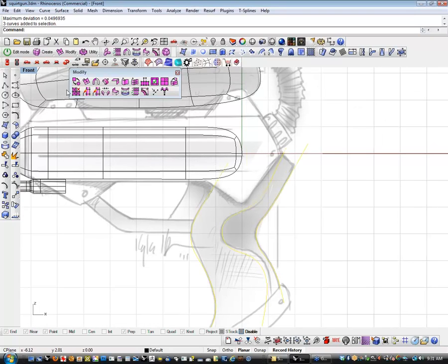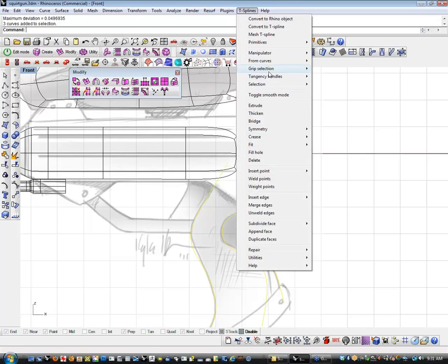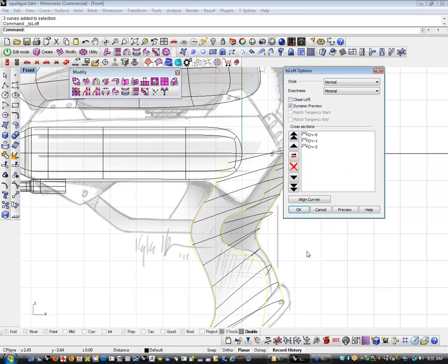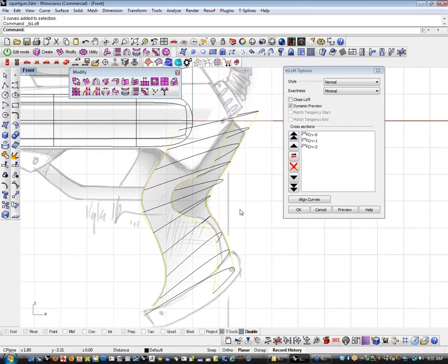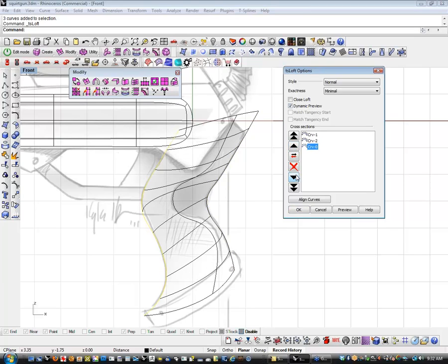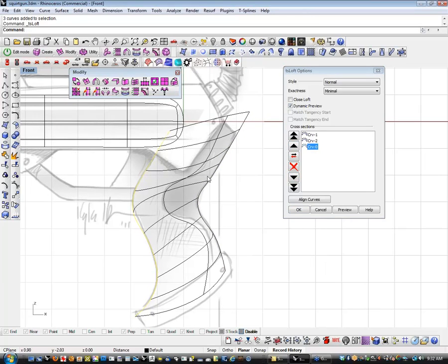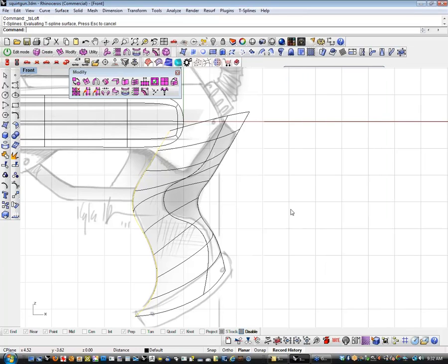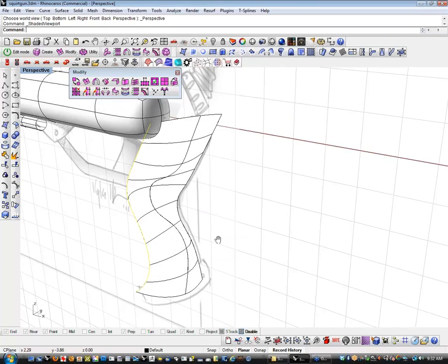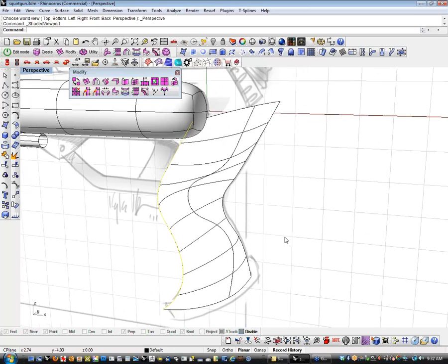And then I'm going to use the T-Splines loft command, and I'll do something crazy and just show it in here from the menu. We're going to just do the loft command. And it's screwed up the order of the curves. It's gone from 1 to 2 to 3. So I'm going to move these around until it is lining up the way I want, and I'm going to say that's okay. And we'll go here, and you'll notice that, again, it's still a flat pattern, but my topology is lined up